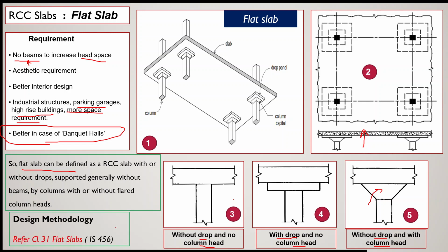For the design methodology of the flat slab, we have to refer to clause number 31 in IS 456. That's why I have advised you, when you are watching the video lecture, you must have a copy of IS 456 in hand, so you can understand it more effectively.